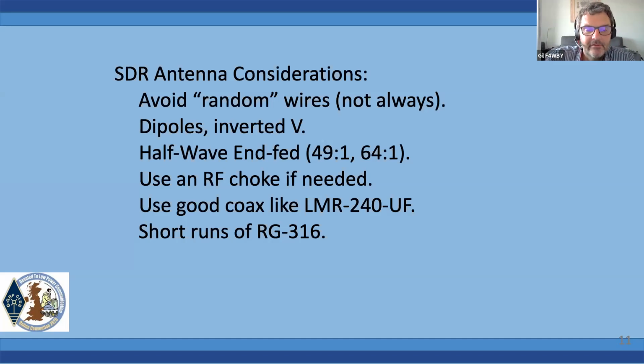Same goes for the RG316, and that's one of my favorite coax also. It's much thinner. It's about the same size as the RG174. It's not as flexible, but it's more durable. Thin coax like that I consider to be consumable. Those cables are not going to last forever. So after a couple dozen outings, usually you're going to change your cable because it's going to have kinks in it, or you get a problem with the connectors and things like that.